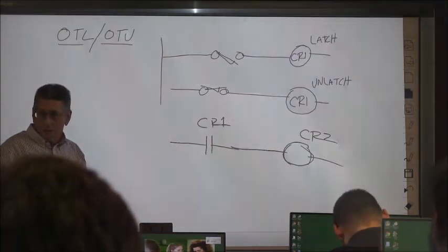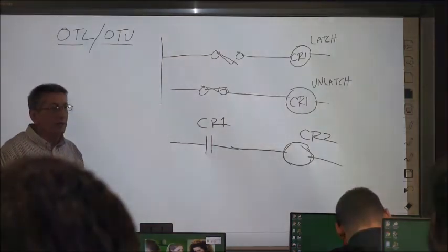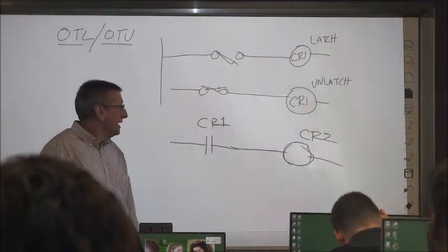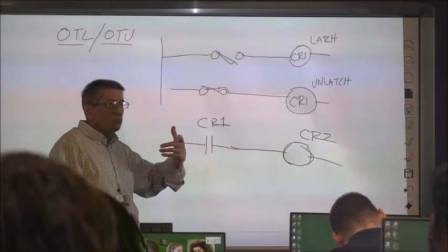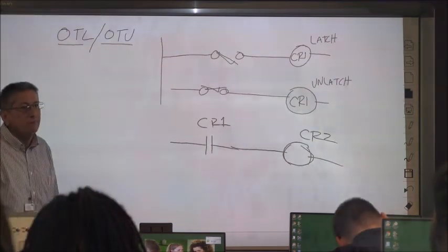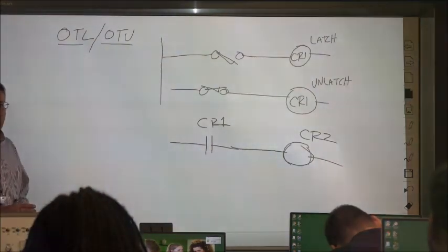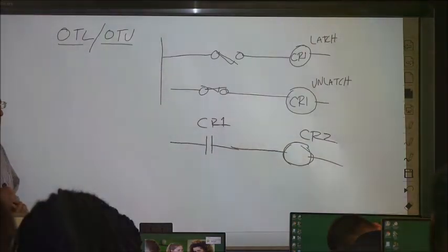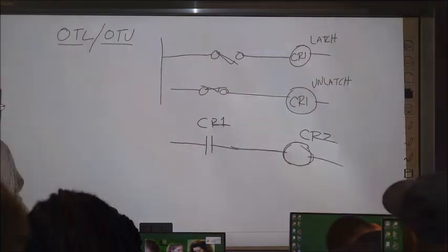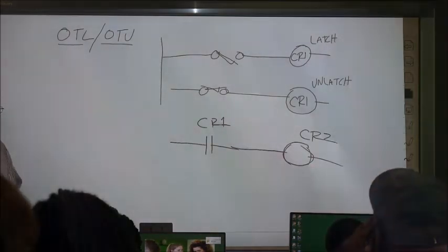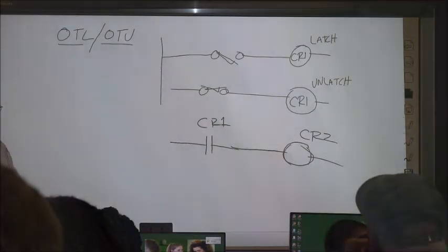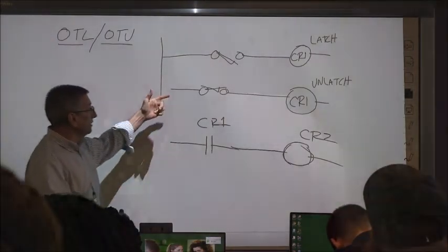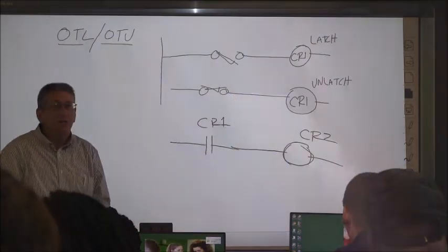This contact stays closed. Make sense? Yeah, that's a good way to think about it. It's like a memory. So latch doesn't need a seal then? Right, it doesn't need a seal. This is like the set reset in Siemens. It'll stay closed indefinitely until you energize the unlatch.